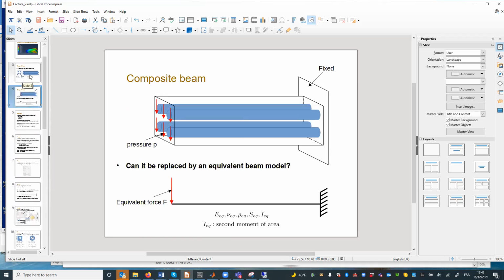So if you do a buckling analysis or a modal analysis, you will have lots of modes. For instance, for a modal analysis, you will have the flexural, the bending modes, the first one, the second one. You will also have a torsion mode, okay? But if you use, for instance, a simple 2D model, you will have fewer modes than the number of modes that you will get with the full model.